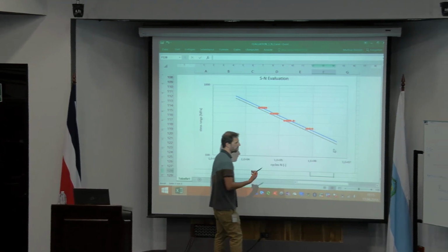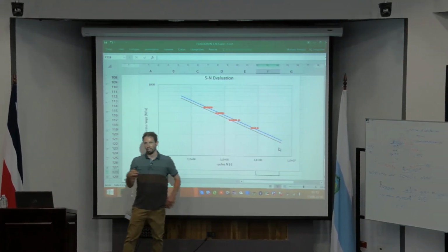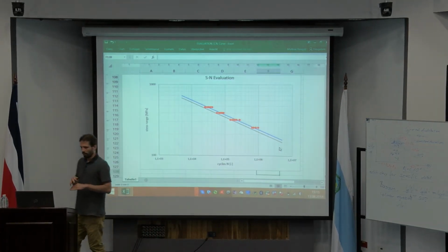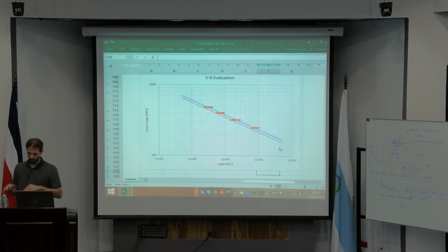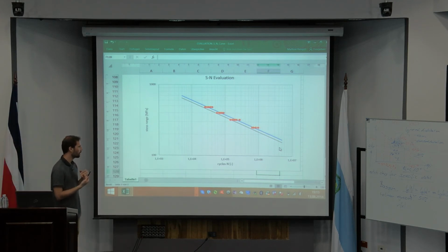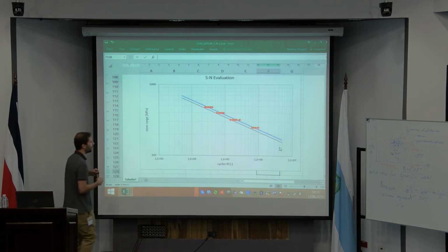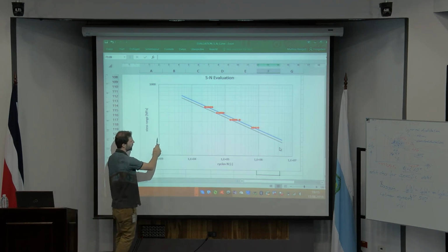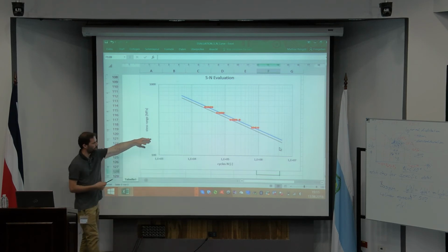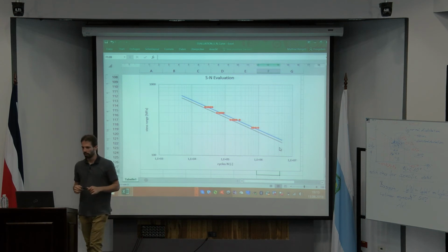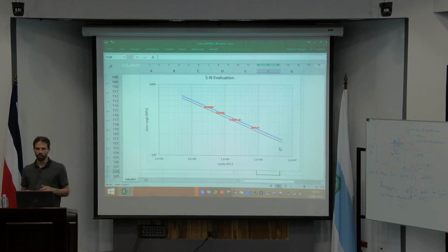And at the end, for example, you have usually some scaling or some equal distances between the notch details so far in the European codes. So, for example, for this specific detail, you have here a value which is around, if you go inside, around the 180 MPa.